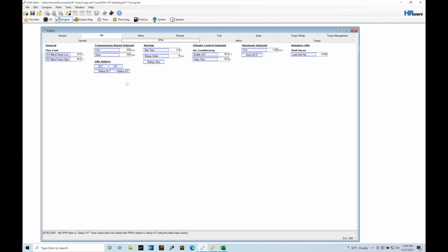If we have movement of the throttle plate, let's say 0.2% closed or 0.2% open, that can be the difference of engine torque being at something like maybe 10 pound-feet of torque to something like 15, or dropping to something like 7 pound-feet of torque. The torque will be very finite in terms of the torque we need to reach a certain desired idle RPM, and we need to make sure we're careful with how we're adjusting.